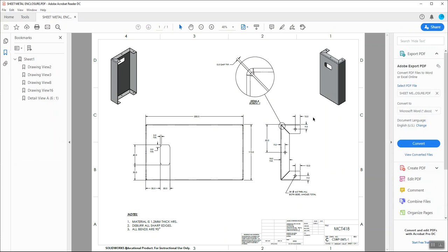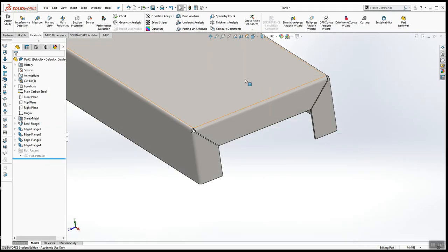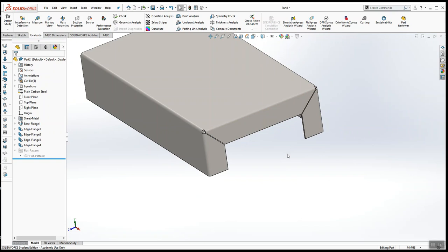So let's come over here and look. We've got 4mm holes, and they're located at 10 in and 9 over there. So let's add these 3 holes, or these 3 points, using Hole Wizard, and then locate them last. So remember, when using Hole Wizard, you have to first pre-select the surface you want to put the hole on.